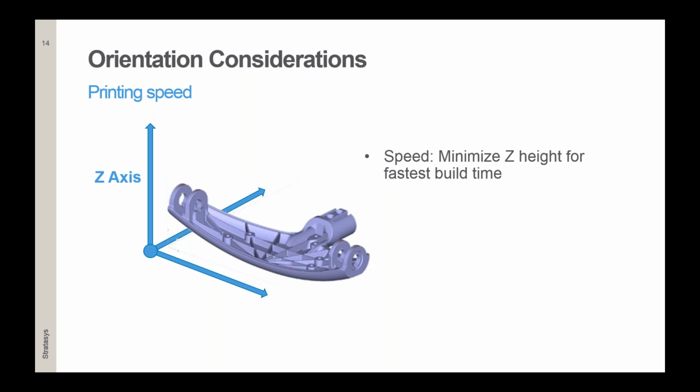Right. So does this mean, Carolus, that the print is quicker because we've got fewer layers? Exactly. The least amount of layers we have in Z direction, it will be printed faster, because we don't have to wait until the build platform moves down and continues our work.